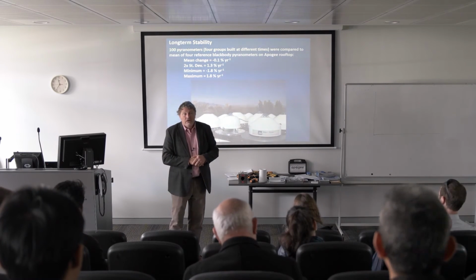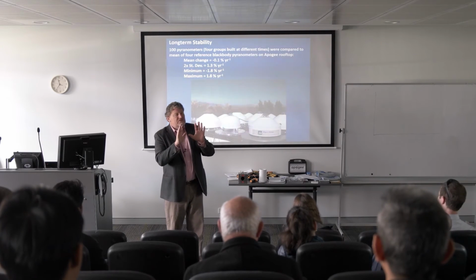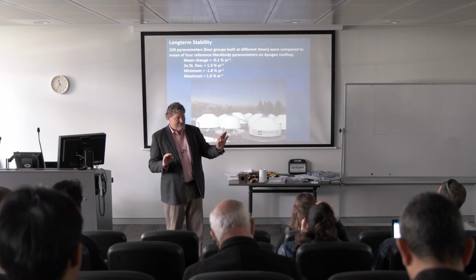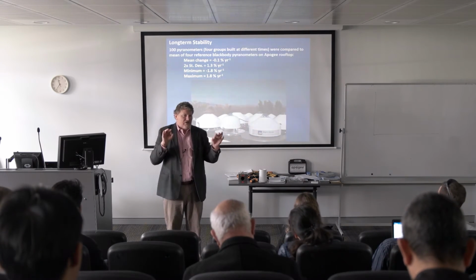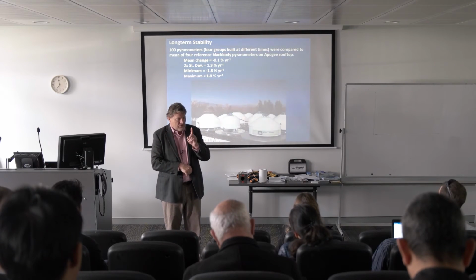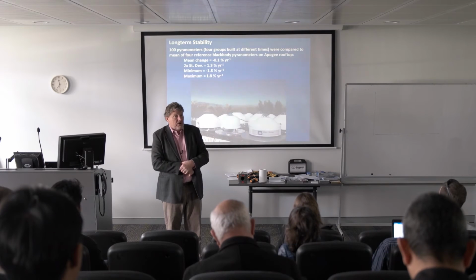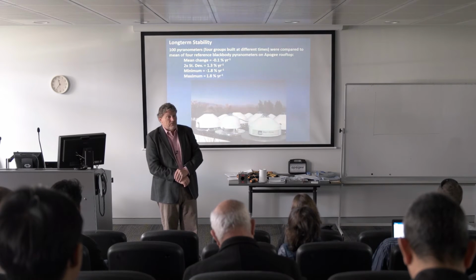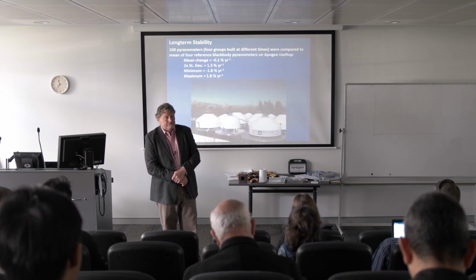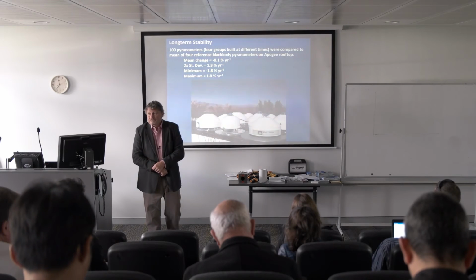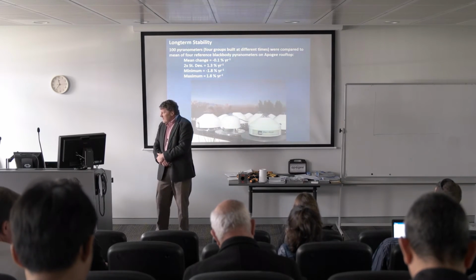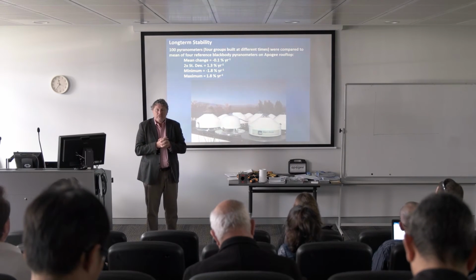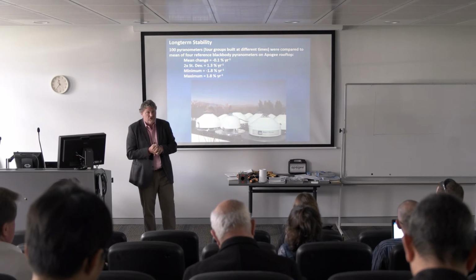What about ones specifically calibrated? Yes, exactly. It's possible to calibrate them, and they're fine, as long as you don't have a mix of sunlight and electric. They just need to be calibrated against a black body pyranometer for that light source. And then they're fine because you know the spectra and you can subsample and predict all of it. I think this is all I want to say about pyranometers and measurement of solar radiation.